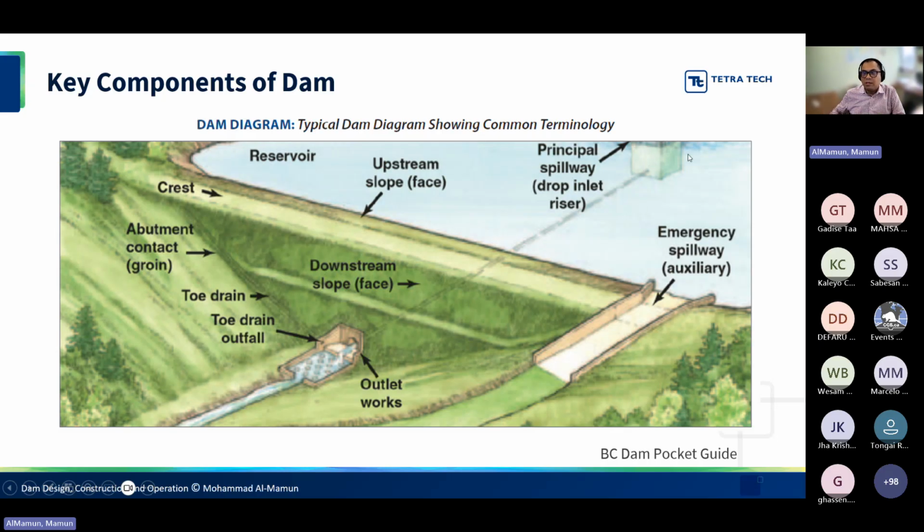So we build this intake structure within the facility. And then for the flood control or the level control for the facility or emergency situations, we have to construct a spillway at some part of the dam, or sometimes you put it outside the dam. The idea is that if there is a big surge of water or the water level rises, we let the water pass through that spillway safely, and that will prevent the overtopping of the facility.